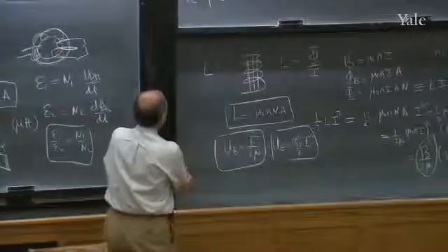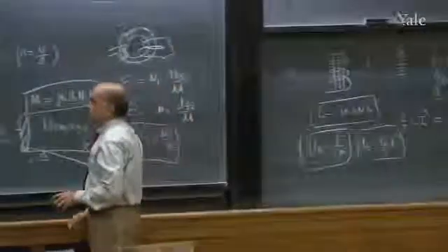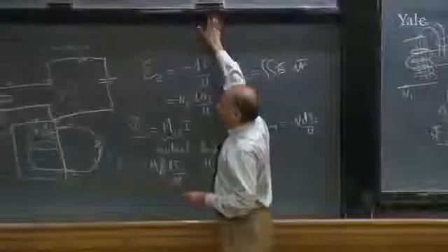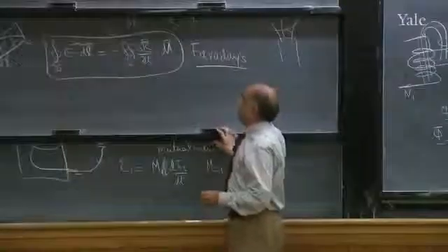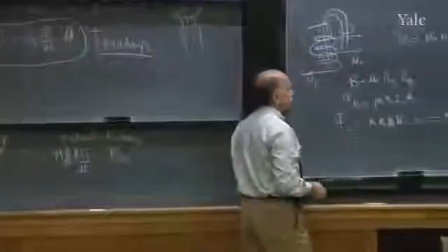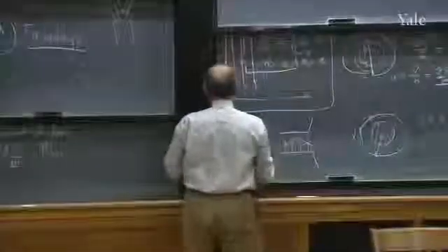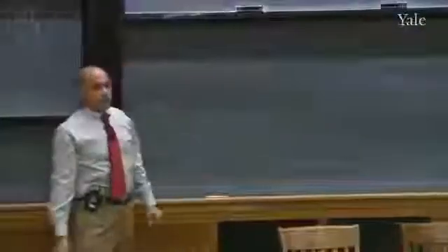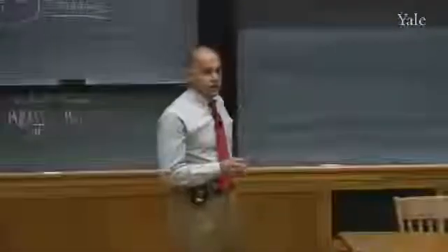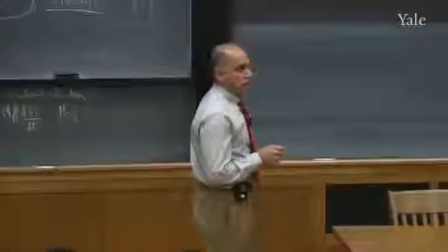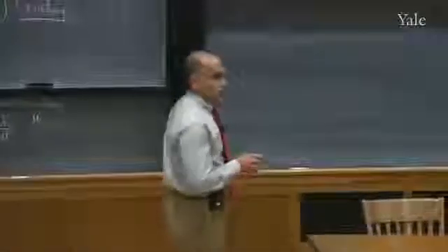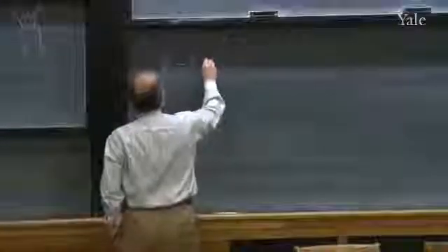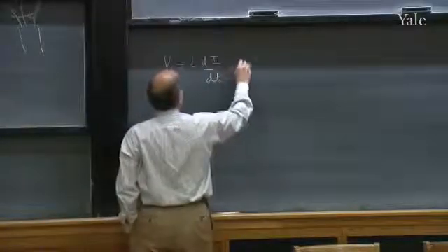So let me summarize what you should remember from all of this. When you have a circuit element called an inductor, it is just a coil of wire that's wrapped around some solenoid. When you change the current through the inductor, it's going to fight it. It's not like a resistor. A resistor fights any current. An inductor fights only a change in current. So that's all summarized in this equation. The voltage is equal to L di dt plus Ri.